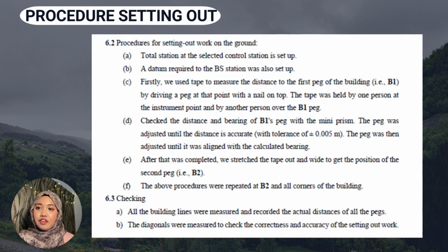The setting out survey is a continuation of a tachymeter surveying where the proposed new structure is drawn in the survey drawing. The procedure included establishing on the ground the positions and elevations of building lines and road alignments specified on construction plans using various techniques and tools.